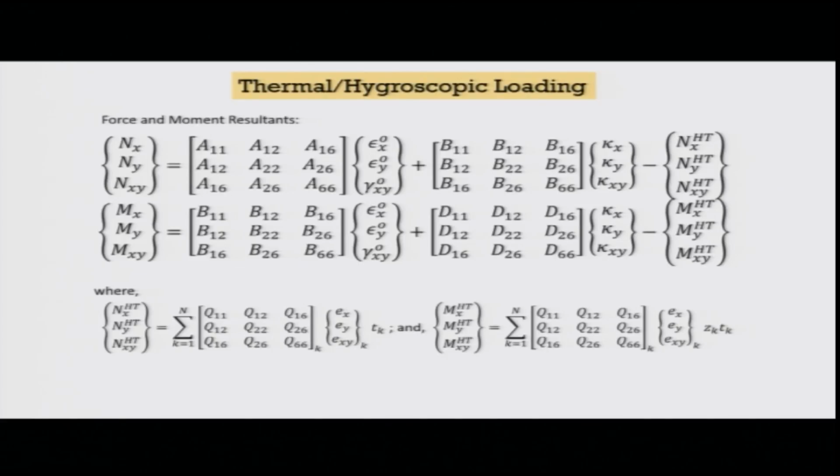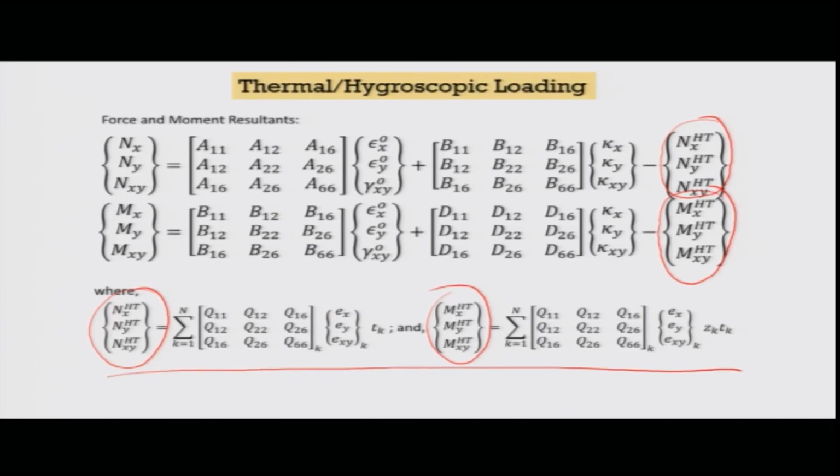So, if I do that, we can actually represent these additional terms in the form of additional loading, as you have seen that N or M, each one of them is giving additional loading in normal stress or additional loading in moment, and they are defined by this relationship. So, this is a simple extension which will be useful in shape memory composites and also in other simple composite systems, but for a smart composite like shape memory it will be also useful.